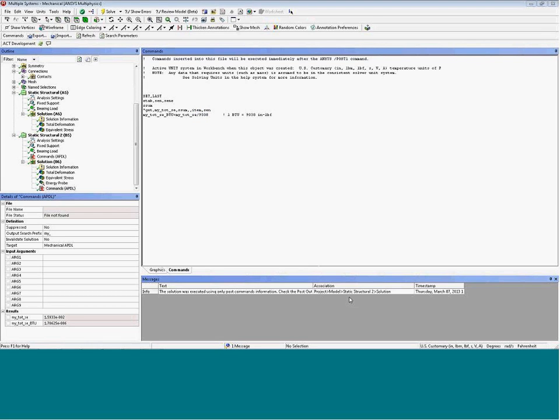This has always been one of the concerns with Workbench: the lack of consistent units in the results. Workbench converts all the British thermal units, or basically the BTU quantity, into equivalent pound units when it goes into classic ANSYS. So when you export or run the database, it's going into classic ANSYS. All material properties, loads, anything that needs to get converted to consistent units does. That also means that in post-processing, those results are still in those consistent units. Workbench converts them back. So really the key here is just to be aware of that.